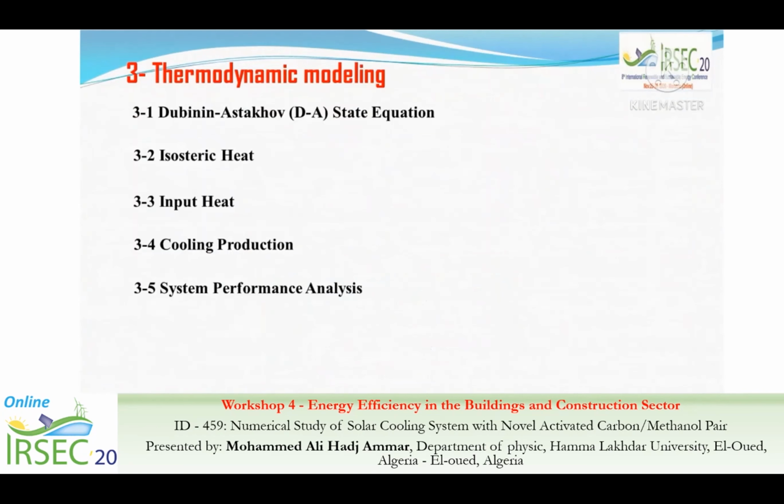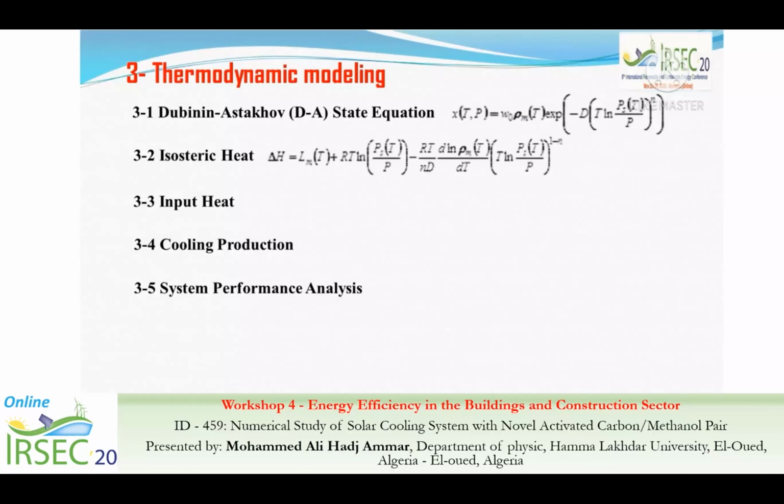In the following, the system thermodynamic modeling is based on the Benedict-Webb-Rubin state equation, isosteric heat, input heat, and cooling production. To evaluate the performance of the system, two parameters were selected: the system COP, which is calculated, and the daily ice production, given in kilograms.